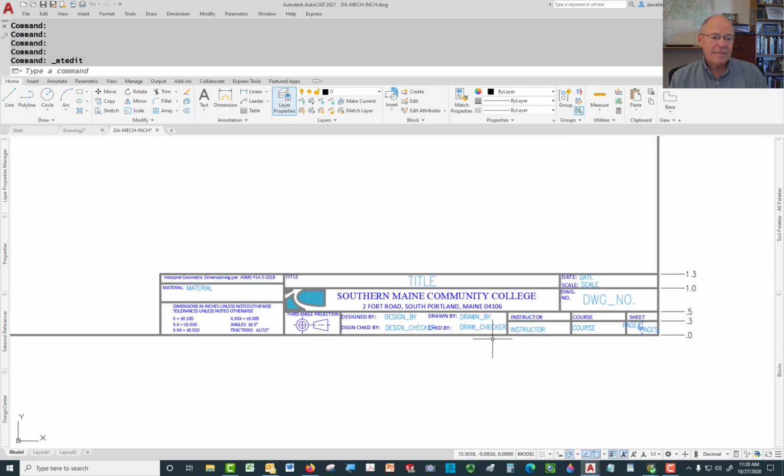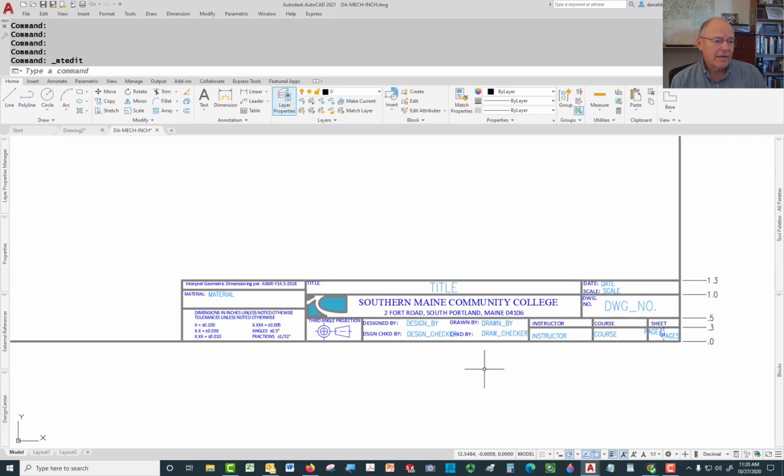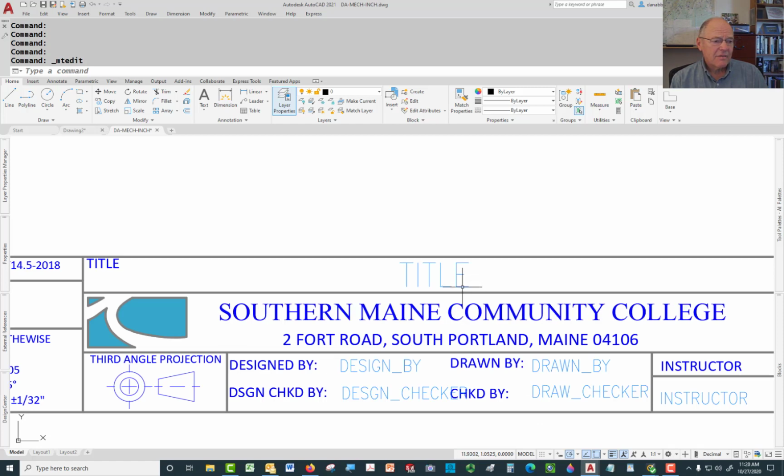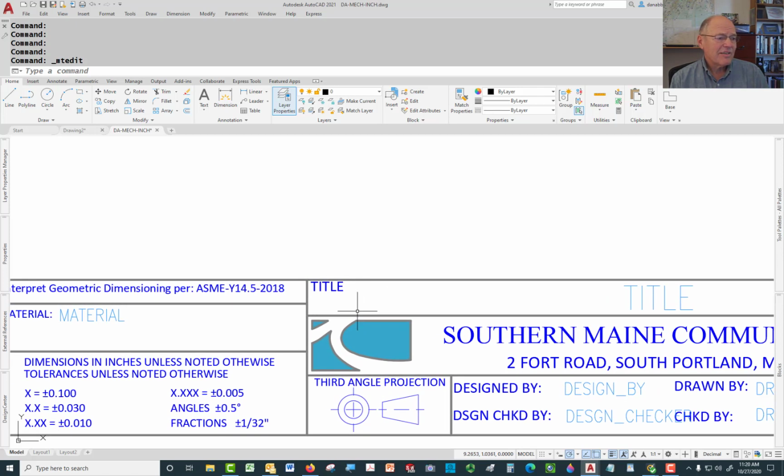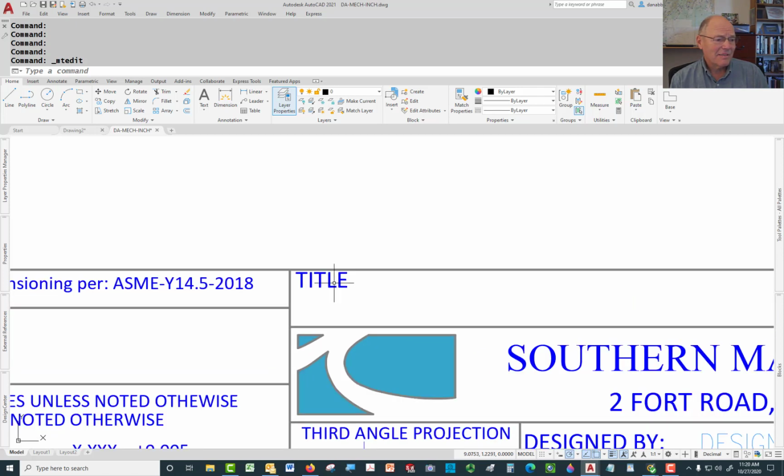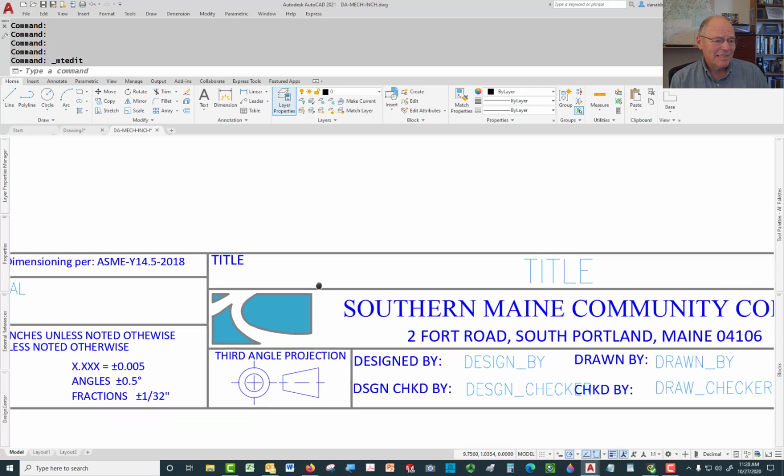And again, these dimensions are simply the dimensions I used. Frequently, if you look at title blocks provided by SolidWorks, for instance, they're this great big, more rectangular and much higher profile title block. Personally, I think that gets in the way. As far as text goes, Roman S is what I use in AutoCAD for the text itself. I used Calibri, or Calibri, I don't know how to pronounce it, for the little tags, just because it makes them a little bit darker and smaller.